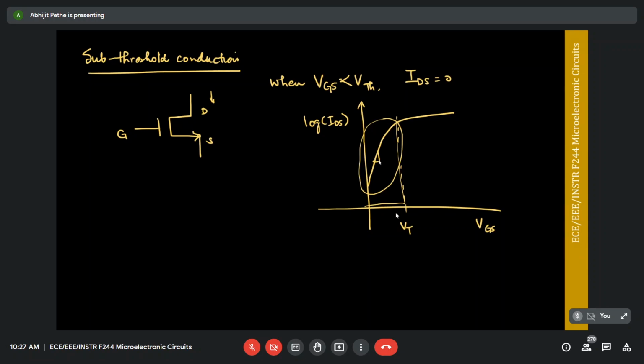Okay. So those are things I want you to remember. We will continue to use the square law, and will not diverge much from it, but these are things to keep in mind about its limitations. Unfortunately, because this is an online semester, we're not doing Cadence with you. But when you do Cadence, you'll realize that the square law model is a good place to start. It gives you a good starting point for design. But eventually, design needs to go using the right SPICE models, developing further off the square law. So the square law gives a very good starting point, and then you go in and optimize it further.